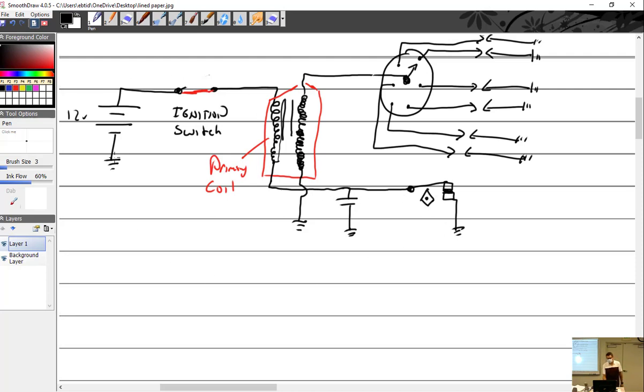So at the moment that I turned on the ignition switch and the points were closed, what happens? All right, so we've got current going through the primary coil. Current going through the coil creates what in the primary coil? Relative motion or voltage? Not yet. You got voltage. Magnetic field. Okay, you got voltage going through, there's amps. When you got a coil, you've made an electromagnet, right? Yeah. So now I have this electromagnet, and the electromagnet is probably, well, it's wrapped around an iron core. It doesn't look like that in the drawing, but it is. I've shown you guys the little coils right here. Coil around here somewhere. There we go. Thanks. So here we go.